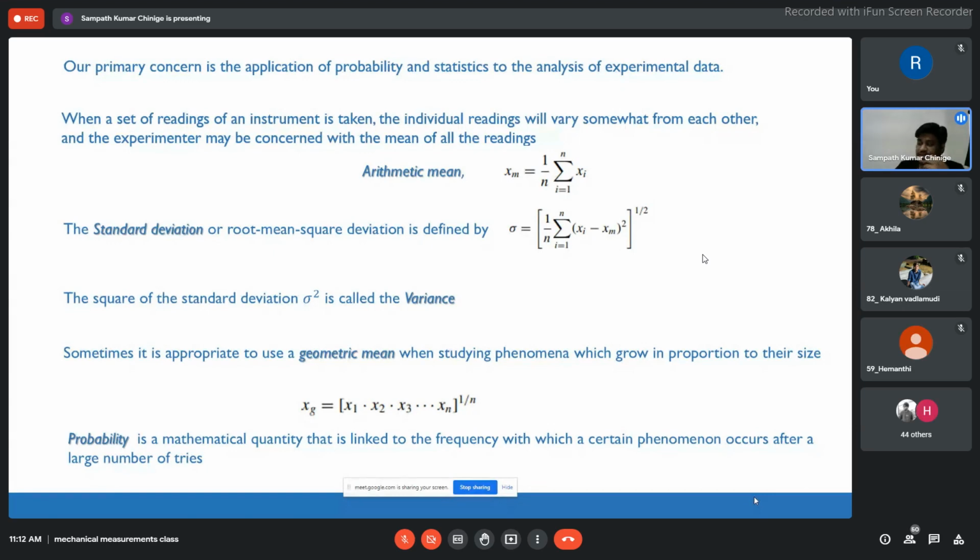So for multi-sample experiments, you can always use the statistical analysis, but for single sample experiments, sometimes it becomes difficult to use the statistical analysis. But the costs incurred will always restrict us from going for a multi-sample experiment. As an experimentalist, buying one instrument and measuring itself is difficult. So again and again, with different instruments and all, is not possible. So the basic statistical ways by which we measure the random error, I am giving out here.